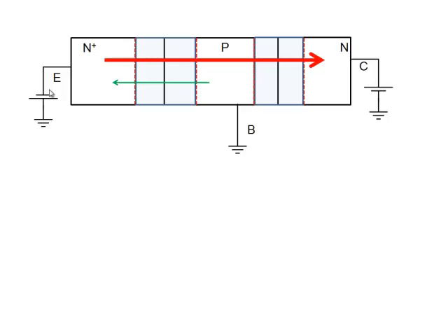Do we see that? Because what is the collector current really equal to? These electrons. Where are these electrons coming from? They're coming from the emitter-base junction. So if I change this voltage, how do you think this current will change? It changes exponentially because it's a PN junction. The number of electrons that are injected will change exponentially with this voltage, which means what? The number of electrons are very sensitive to the voltage that I apply at the emitter. Something changing exponentially means very sensitive. On the other hand, do you think this voltage will do anything to the electron here? This voltage here?